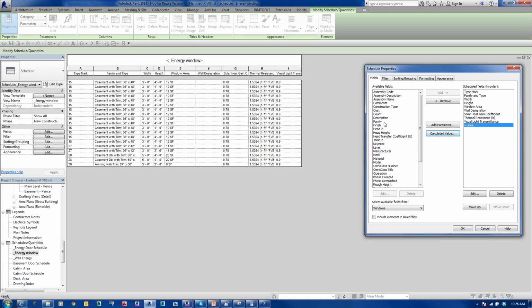So we don't need the thickness of the wall, except if I was doing log. I have a width parameter in there for my log that gives me the actual ratio of what the log parameter is. So I use that for another purpose, and I apologize for that. So I have to go inside of my wall parameters and grab the length one and then multiply that by the height or my ceiling height to get that value out there. So it's a good catch, James. I realized that after I plugged that in there, and I'm like, oh, that's not actually giving me the right value. But when we're dealing with logs, we have to deal with the whole ratio of the log. What's the actual, I forget the proper terminology, but the true thickness of the log as it's being tapered down. Okay.